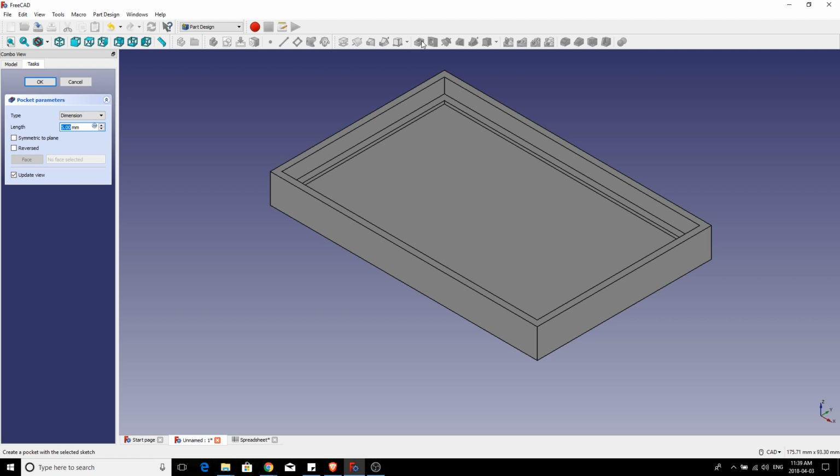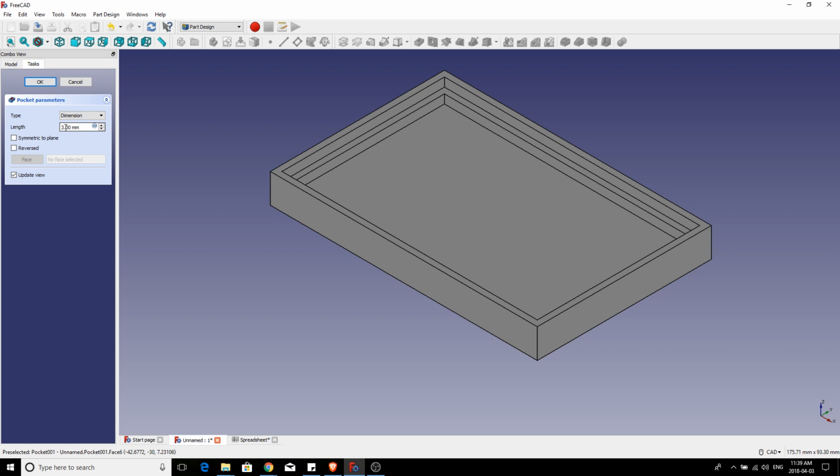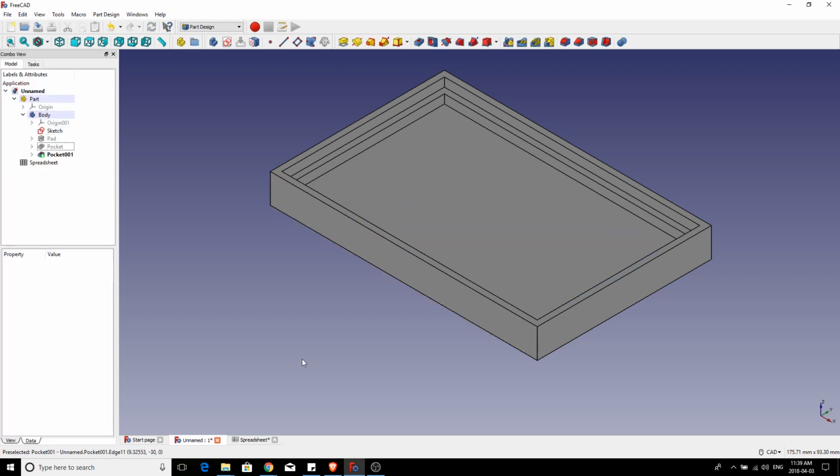But would the lid thickness really change based on a change in the dimensions of the credit card? Not really. This particular stat is going to be more based on what material we want to build that lid from. So I'm saying in this case 5 millimeters is a little bit deep. That's not going to leave a lot of room for putting cards inside the thing. And maybe I'll back it off to 3 millimeters. And this one, we can pretty much just leave as a constant. And that, my friends, is looking pretty darn good.